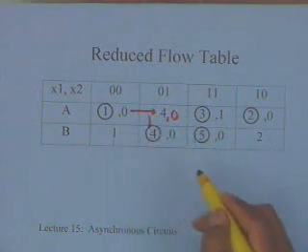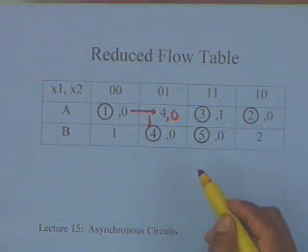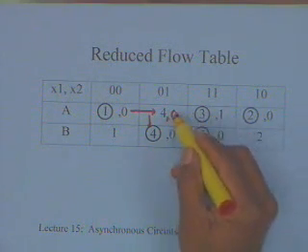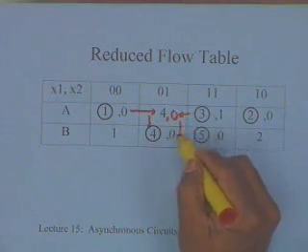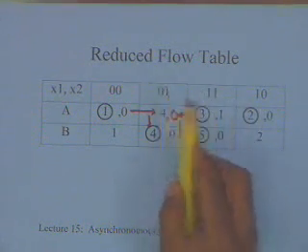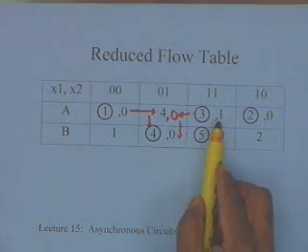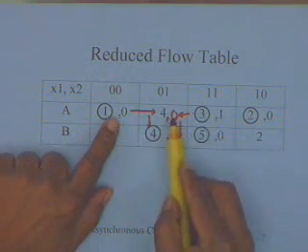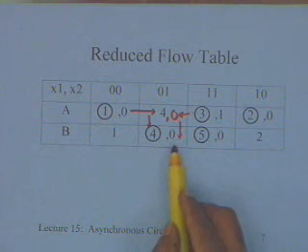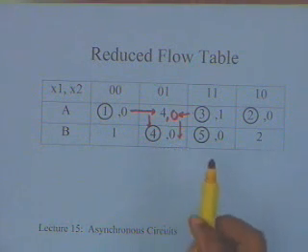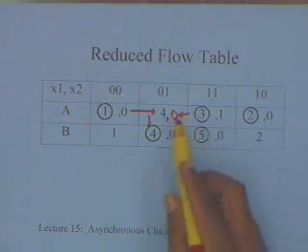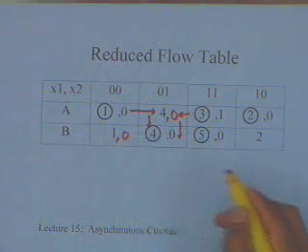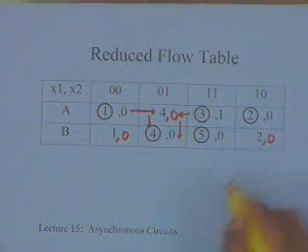And you have to also be careful, because this path is not the only path that is important over here. What is the other path that is going to come? I am not going to come from here to here because it is a fundamental mode, but I will come from an input 1 1 to 0 1, so in this case 1 0 0. Now if I try to assign, for example, 0 based on this and 1 based on this, I will be in trouble. So that is the reason I just assign it based on the earliest possible output. In this case the two places from which this transient comes are different. Of course here there is no such issue, here also there is no such issue.